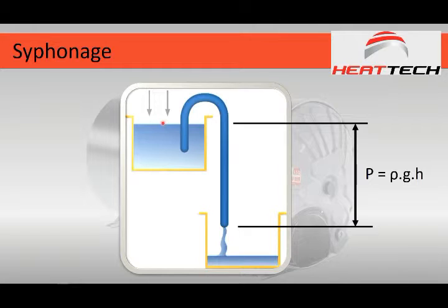The pressure at the top, where the laser point is showing, let me see if everybody's screens are updated. The pressure at the top is therefore higher than the pressure at the bottom. And that is why I even included the formula. The pressure equals the density of the liquid, of water, times gravity times the height. So the higher the height, the bigger the pressure difference. So there's a pressure difference.